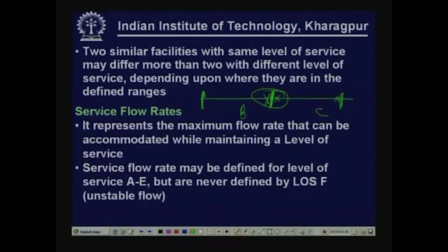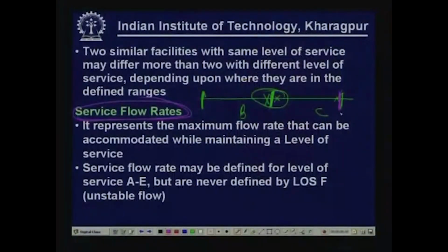Coming to the concept of service flow rates, this concept is again related to level of service. Service flow rates generally represent the maximum flow rate that can be accommodated while maintaining a level of service. That means, for a given level of service range, what is the maximum flow that can be accommodated within that given level of service? Obviously, it goes to the boundary condition.